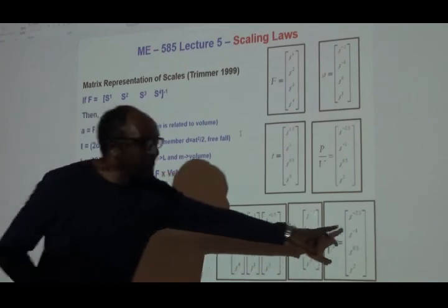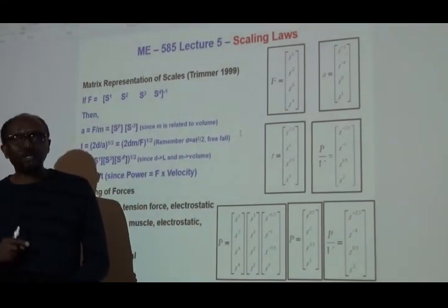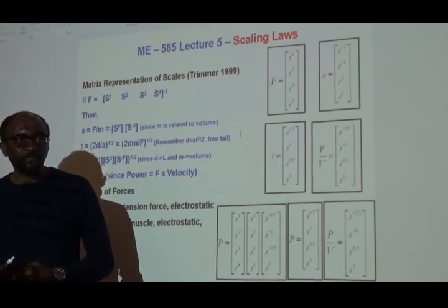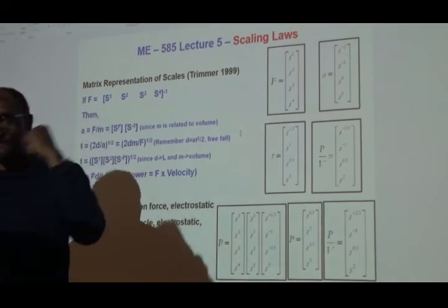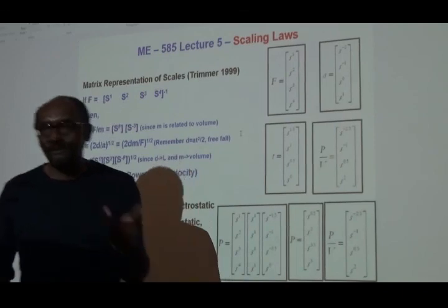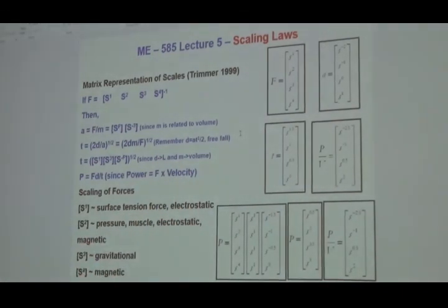But the power density actually reduces only by S to the power minus 1, just by the inverse. It doesn't reduce by 4 times. For example, if I cut by 3, then the force would have reduced by 9 times, right? If you reduce the length, the force will reduce by that much. But the power density is just the inverse. It's 1 over 3, which is favorable. Okay, I don't know if you're paying attention. So 1 over 3 is much more favorable than 1 over 9.